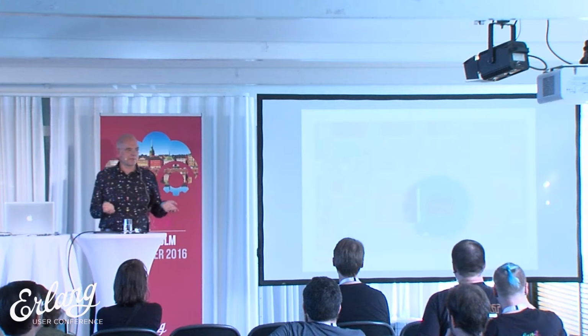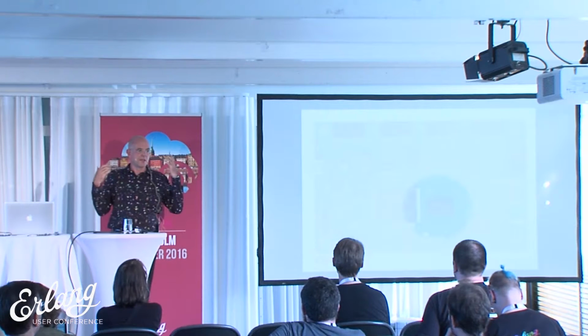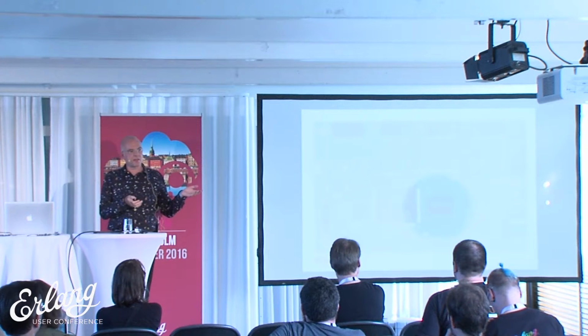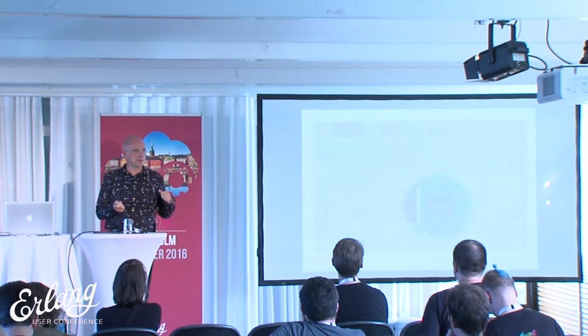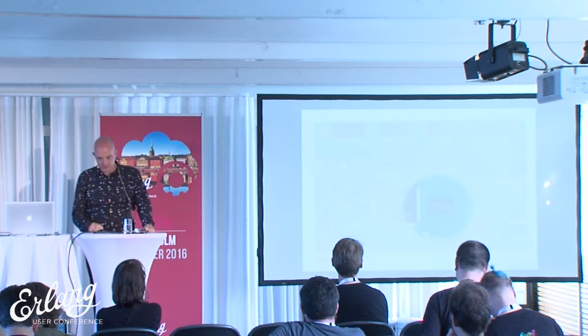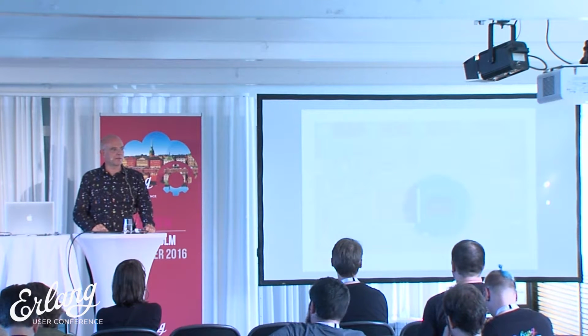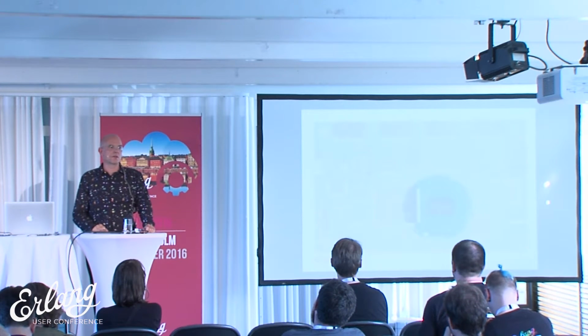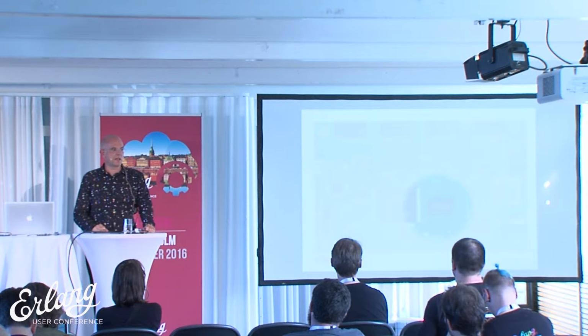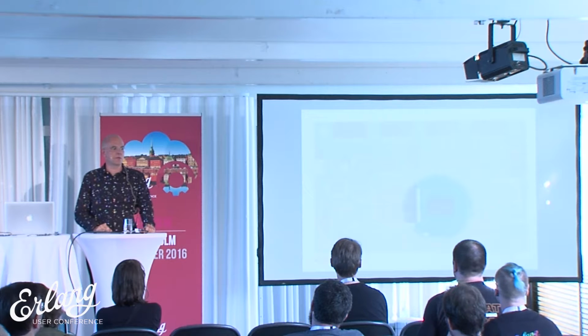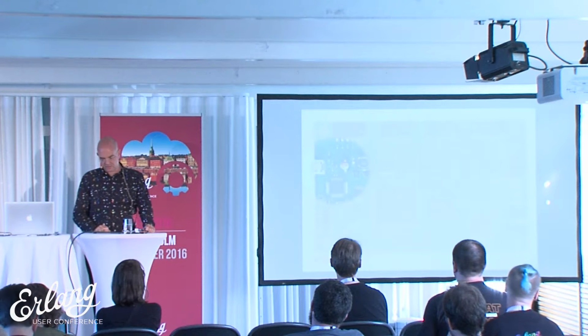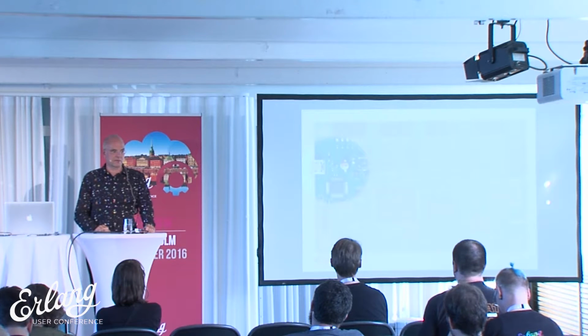When we boot, we load stuff into some memory. There is some memory on the CPU because it's actually an embedded automotive CPU. It's actually for multimedia applications in the car. And so the on-chip memory is only 384K. So that's a little bit small for running a normal Erlang. And so we added a little bit more memory, and since the CPU supports an SD-RAM interface, we added one SD-RAM. 64 meg is plenty for Erlang in this setup.